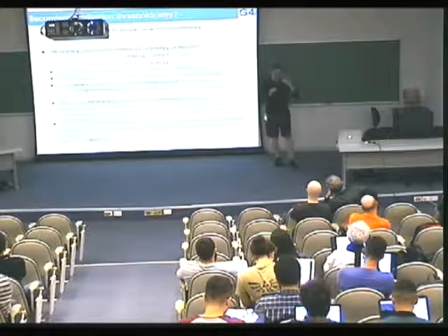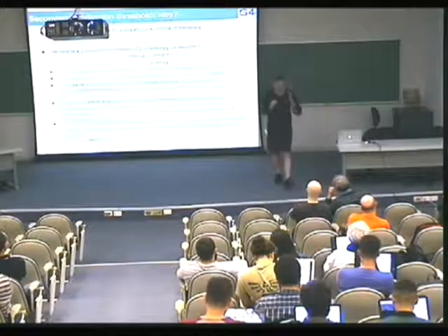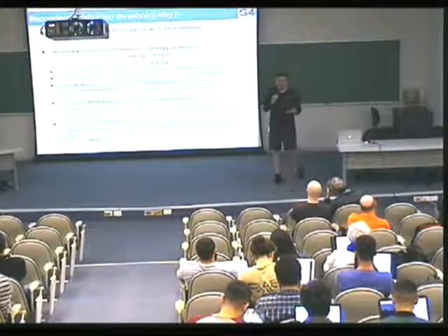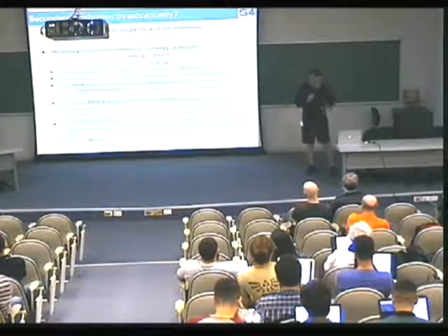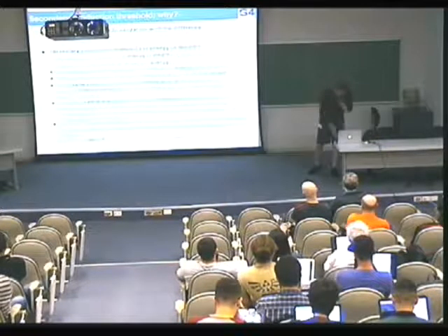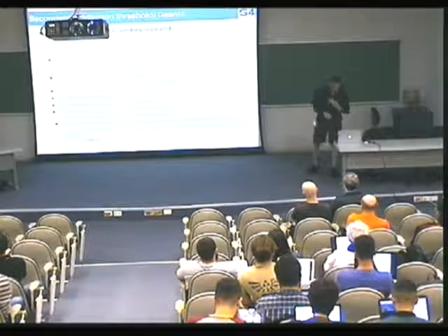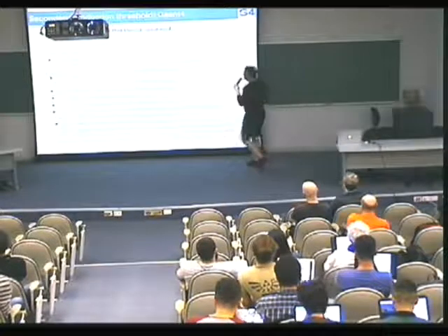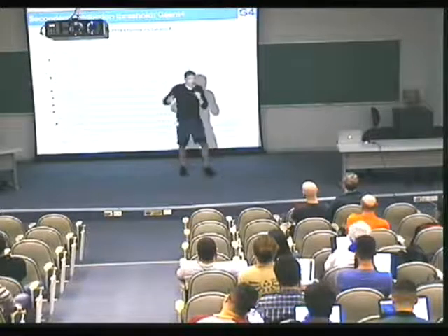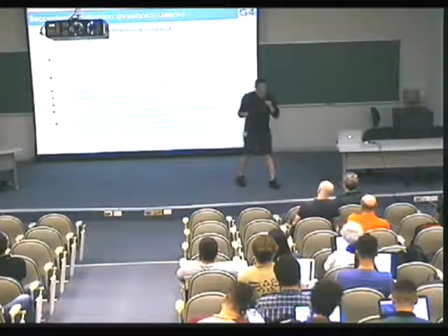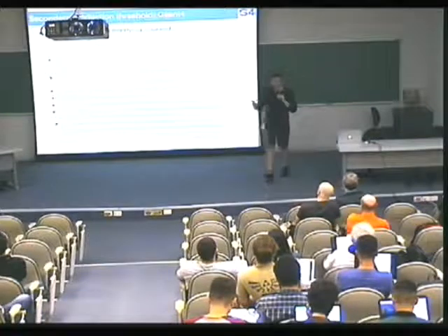So it becomes really, really complicated because you need to think in advance a lot. While giving it in length is easier because this is exactly what you see, what you think immediately. It's much more intuitive. So in Geant4, you give the secondary production threshold in length. It has a default value of 1 millimeter. In case of some predefined physics lists, it's already 0.7.